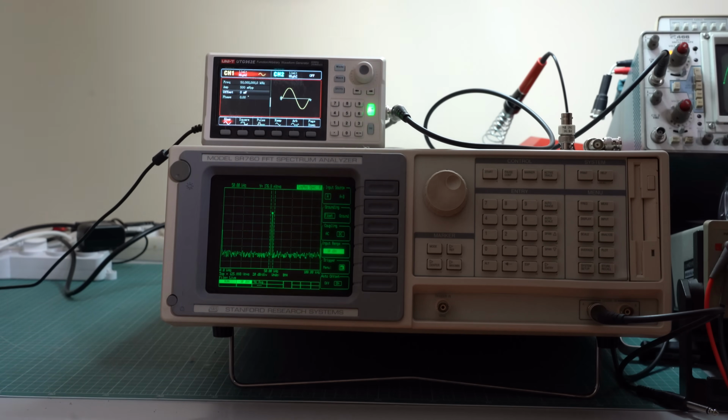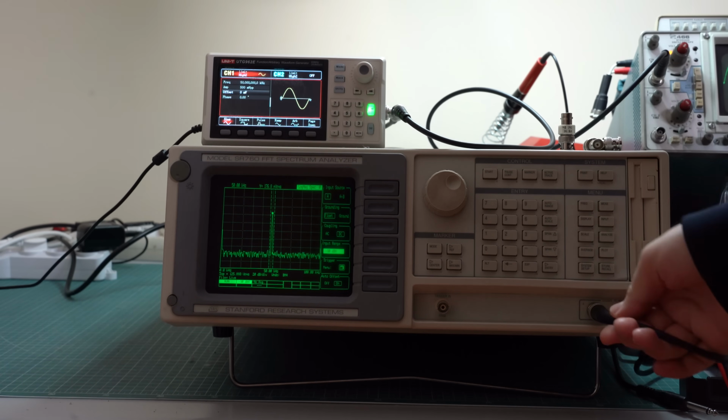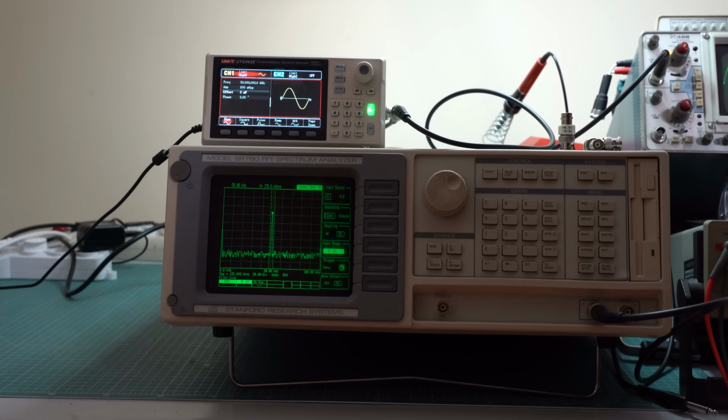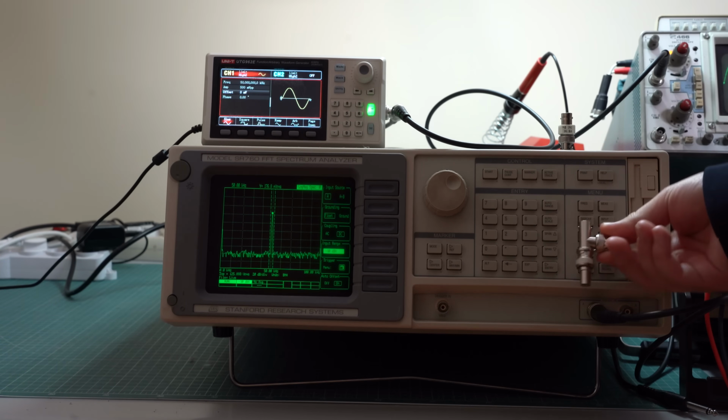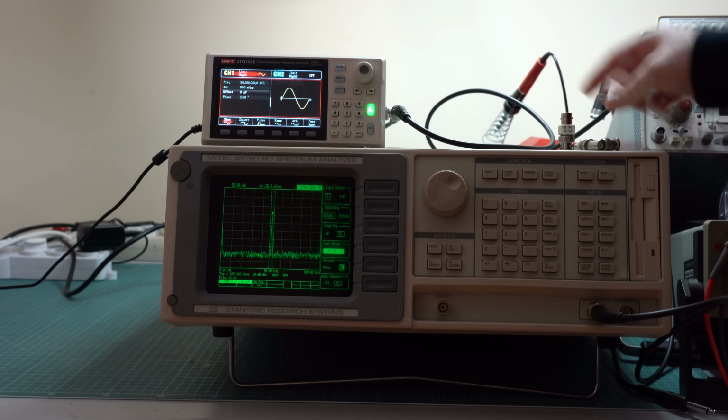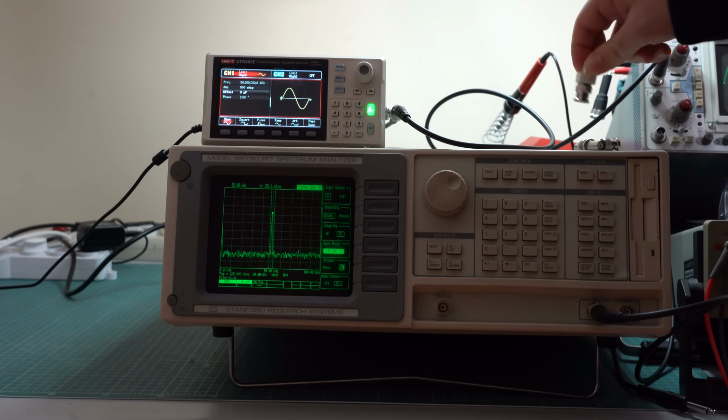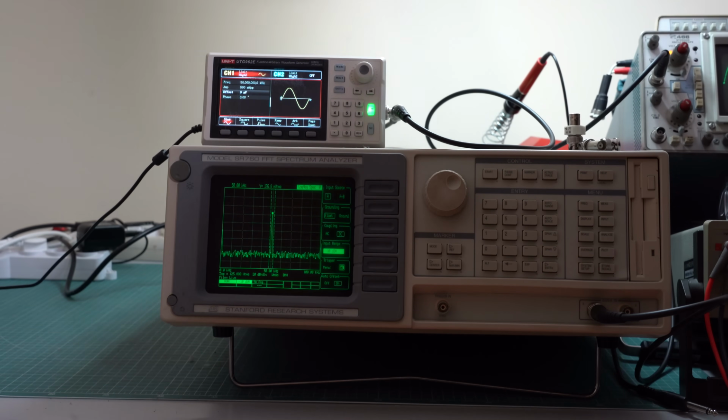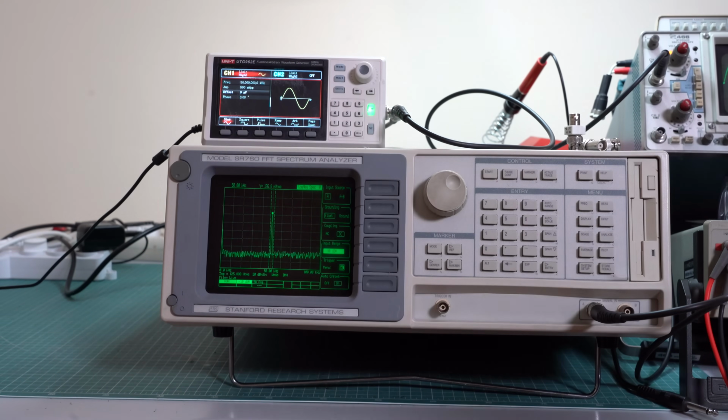And also, if you're working with radio frequency equipment, make sure that this input is properly terminated, usually into 50 ohms. So either the spectrum analyzer can do this, or you have to use an external terminator like this one and a T adapter, or maybe a through terminator like this one. And then with this in mind, we can move on to the settings.